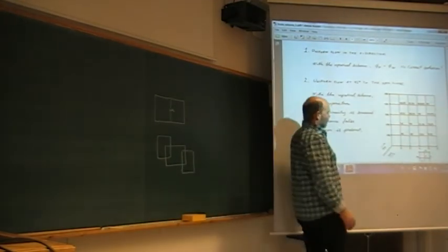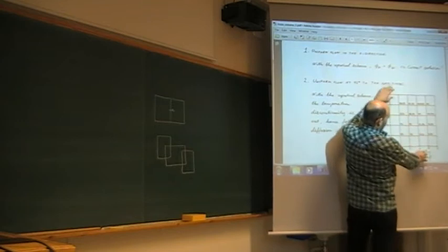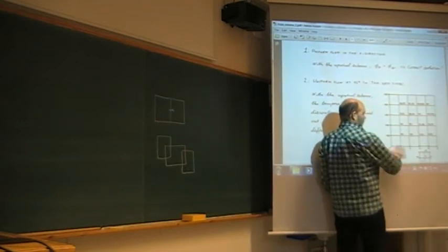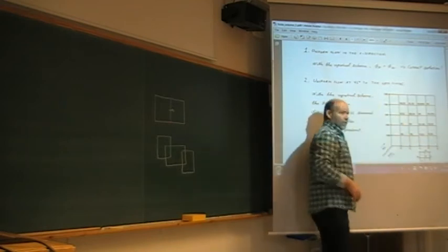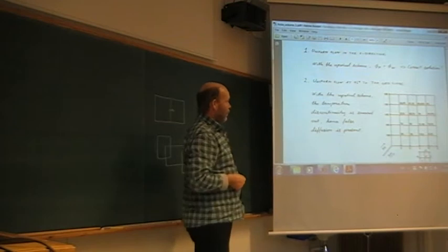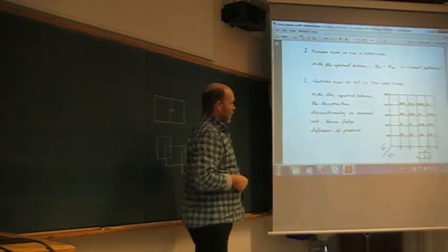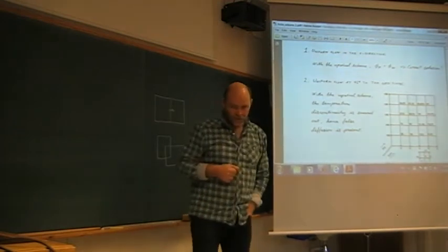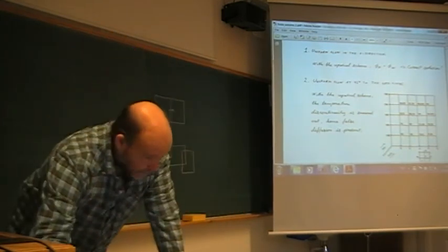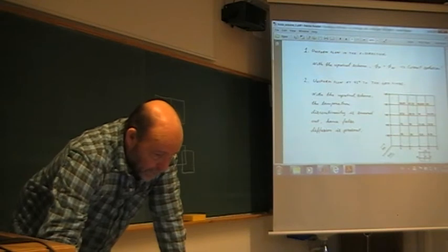It is getting smeared out if you look at the different numbers here. So we will have a diffusion effect present here with the first order upwind scheme. So I think I'll call this false diffusion. And yes, it is a diffusion mechanism, quite clearly.